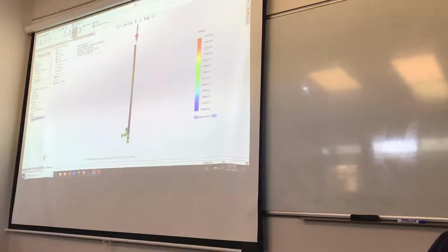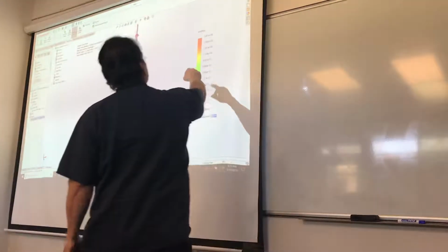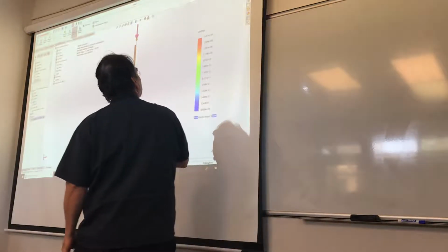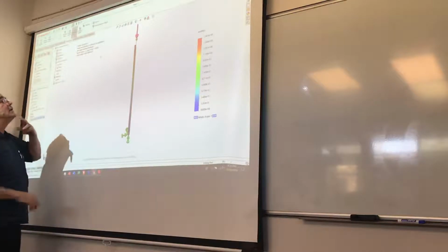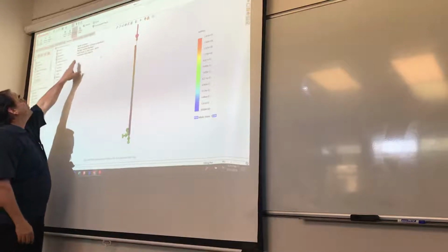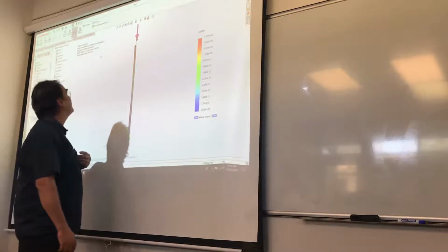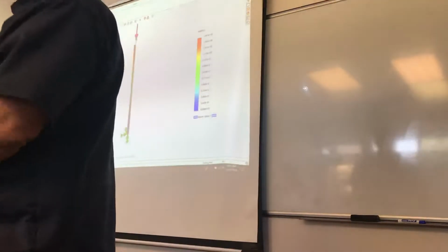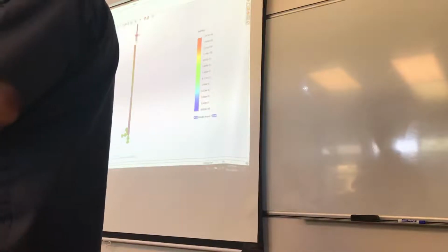Okay. So this was the thing, the results I got up here. I got a thing that said, oh, it's got an amplitude basically 1.49, which means it's deforming 1.49 inches, probably what it's doing. We have a mode shape 1. We have a load factor of 65,795. Now, what the devil is a load factor?